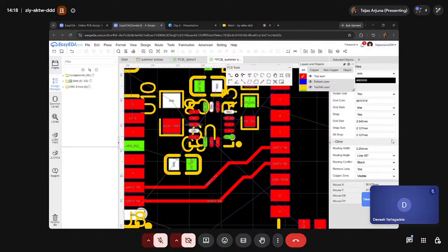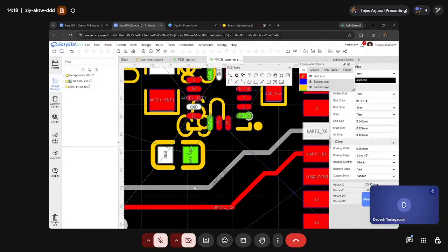The second thing is inductive coupling, which can happen when they run for a long distance. When there is a current spike, there will be a voltage spike. There can be signal transfer, because if you consider this as one inductor and this as the other, the voltage drop here will be mutual inductance times the rate of change of current.